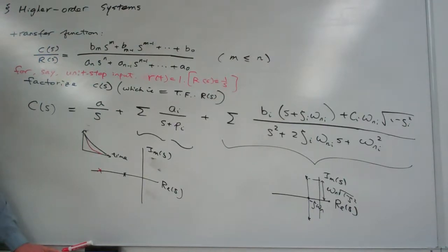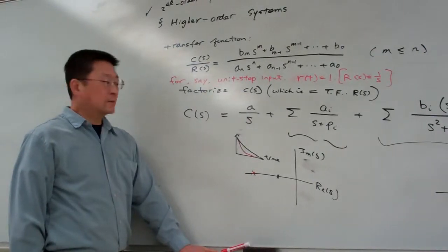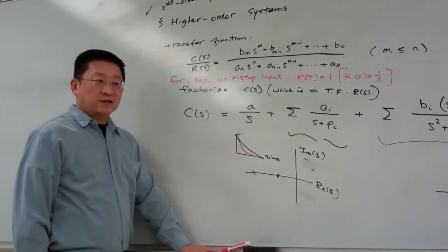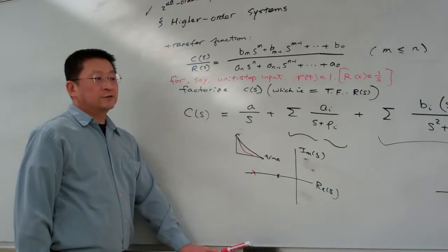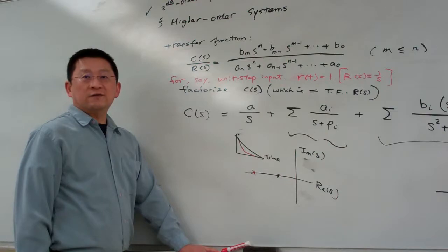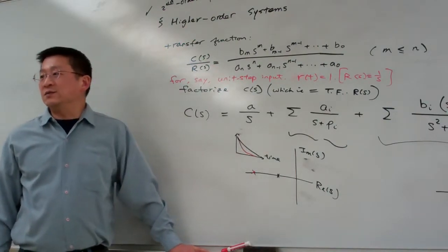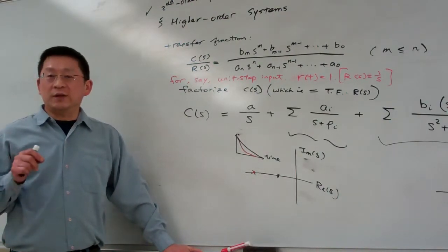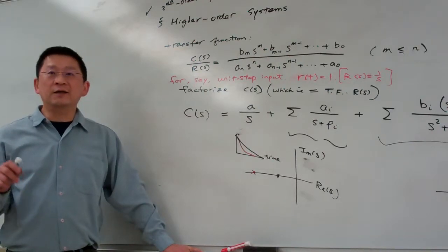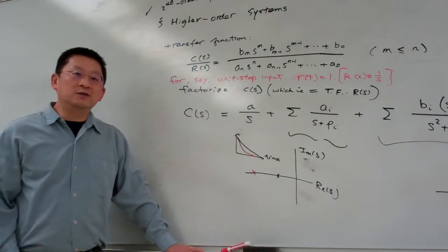From here you might try this. For example, if a system combines slow and fast dynamics, a very good engineering exercise is this: under certain approximations, you can simply ignore the fast dynamics. Why can I say so? Because the system's behavior is in the majority determined by the slowest dynamic component.